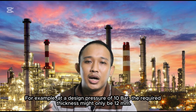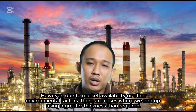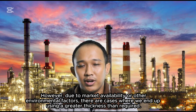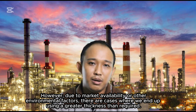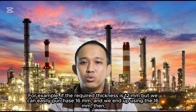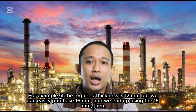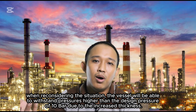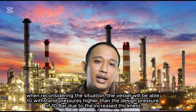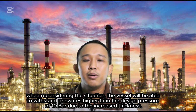For example, at a design pressure of 10 bar, the required thickness might only be 12 millimeters. However, due to market availability or other environmental factors, there are cases where we end up using a greater thickness than required. For example, if the required thickness is 12 millimeters but we can easily purchase 16 millimeters, and we end up using the 16 millimeters, then the vessel will be able to withstand pressures higher than the design pressure of 10 bar due to the increased thickness.